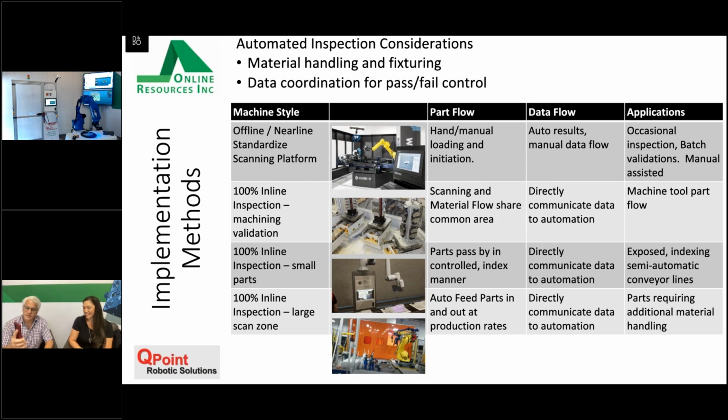And so the ability to see that event recorder camera from here, or not just a phone, but from a desktop somewhere else, make changes. This is the kind of support we really actually enjoy doing. People call, hey, something ain't quite right. Can you take a look with us? Sure. We jump right in. And oh, you might want to look at your sensor on your end of arm tooling. It looks like it's flaking out a little bit. You can go in, disable it. The system will keep on running. They get it fixed, switch it back on again.